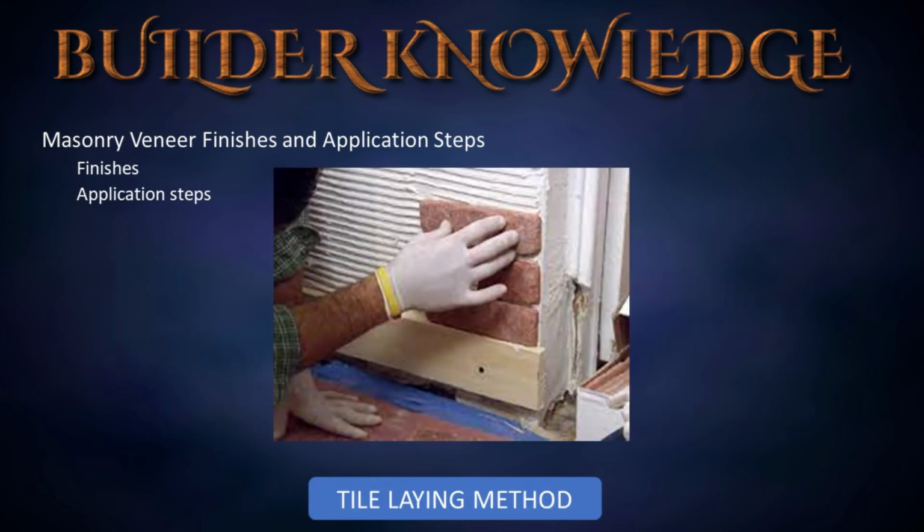Now let's quickly cover the application steps. Veneer is primarily used on exterior walls, but may be used on interior surfaces. It may be applied to concrete masonry units, CMUs, or wood framing. Application procedures follow the same general methods for tiling, except that flashing and drip edges may be required. Bricklaying procedures are detailed in one of our other videos in the concrete masonry section.